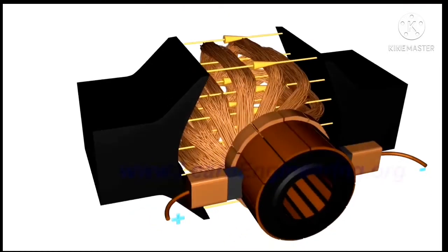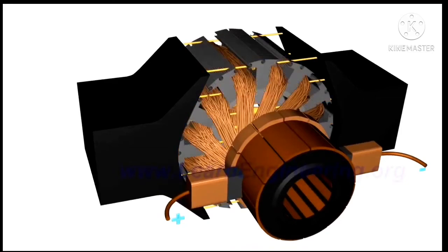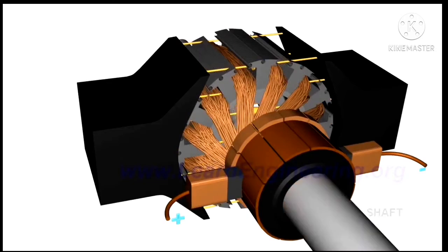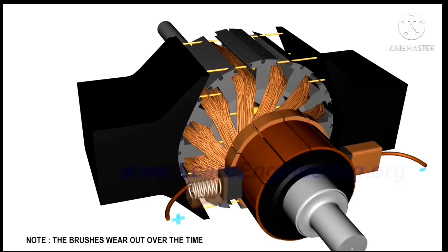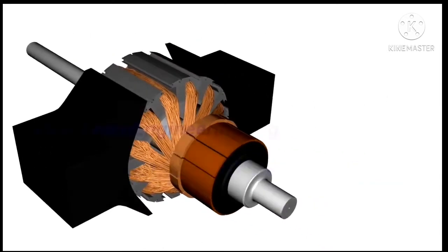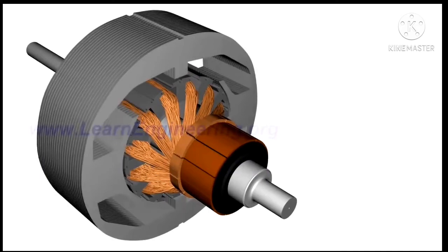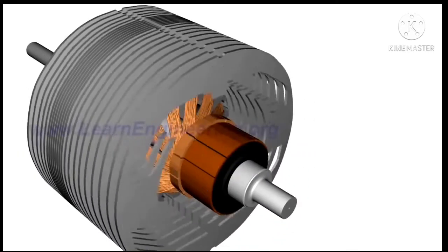In a practical motor, the armature loops are fitted inside slots in a highly permeable steel layer. This will enhance the magnetic flux interaction. Spring-loaded commutator brushes will help to maintain contact with the power source. A permanent magnet stator pole is used only for very small DC motors. More often, an electromagnet is used.